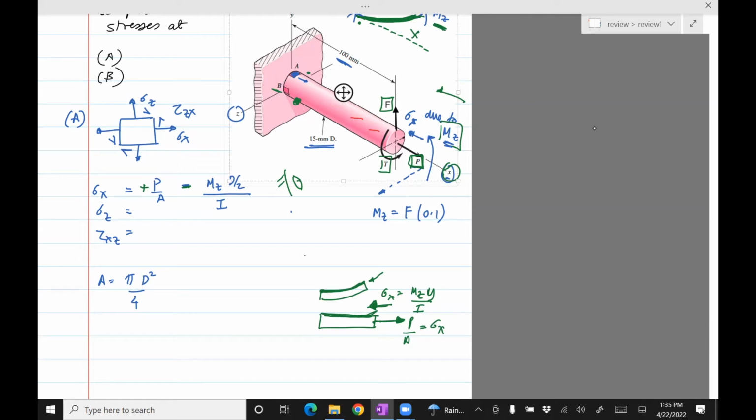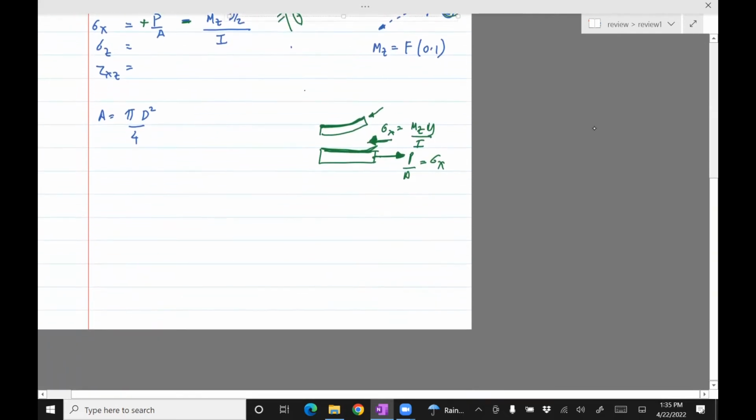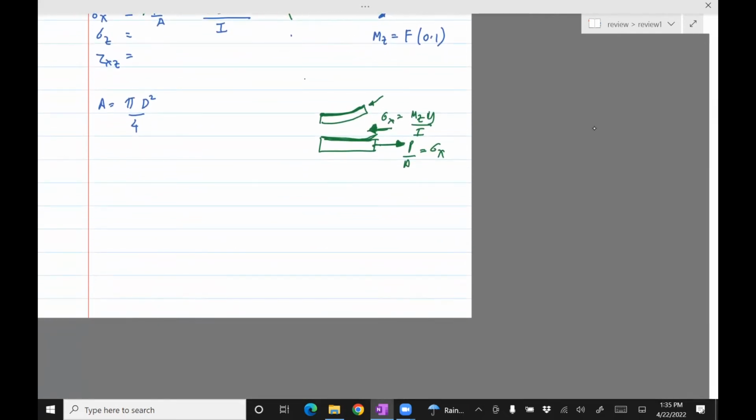So inside of the U, it's compression, and outside, it's the other way. So inside the U is always compression. Yes, so that's a good trick. One suggestion was, once you bend it down, the thing inside the U is always compression, and outside it's always tension. That's always true, so you can remember it this way if you want.